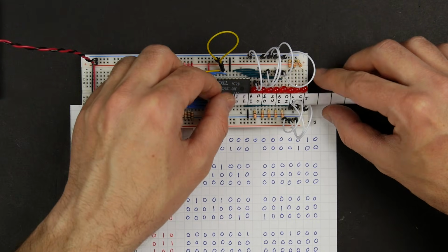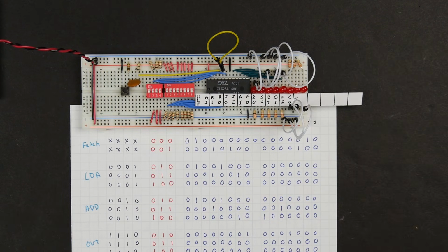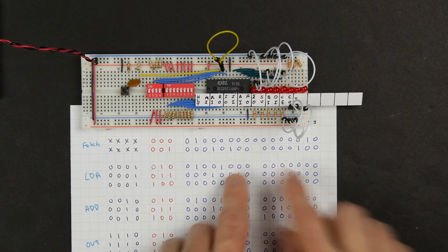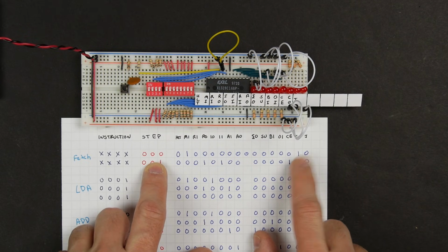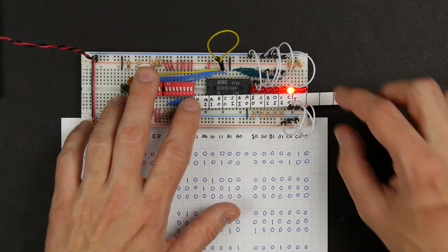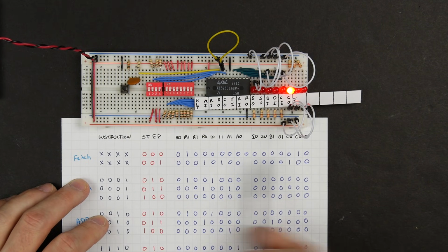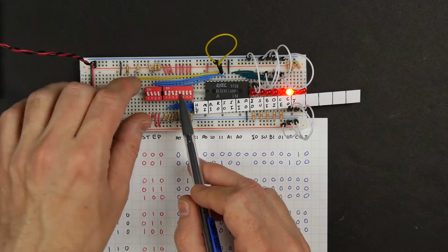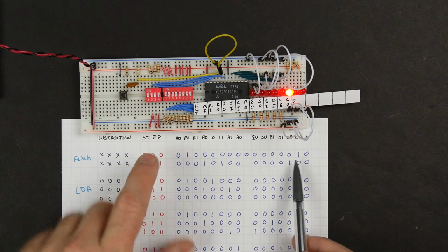And this time around, we're over here programming those bits of the control word. So again, we have to program the fetch. In this case, we're programming this side over here. For step 0, we want the counter out to be enabled, and that's this bit here, counter out. Just like before, we want to program step 0 for counter out into all of the different instructions, so we'll just cycle through instruction 0 through 15. Okay, and so now we have that counter out bit set for all of step 0.